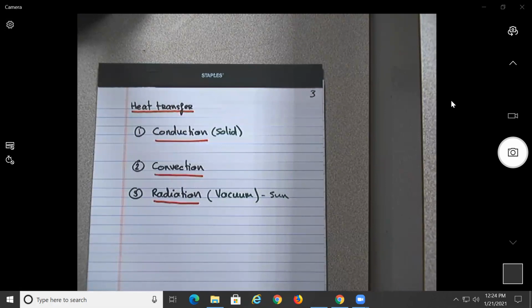And let's say after that you have, whatever, plaster. This plaster, these insulators, are better than steel. Okay? Can you stop the heat from coming in? No, you cannot. You can slow it down, but you cannot stop it. So what is the whole idea about insulation? It is to slow it enough so that you get to the night, no? And now the system doesn't need to work that hard anymore. But you cannot stop it. You can slow it. There's no such thing as stopping the heat.